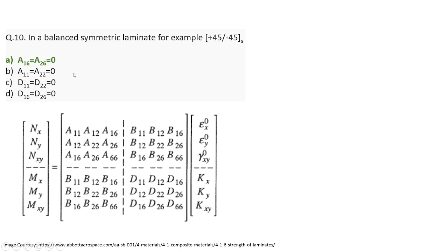But here, because these are at angles other than 0 and 90, in the D matrix, when there is a moment in one direction, there will be rotation in that plane because of this angle. Otherwise, for the force resultant, it is similar to before: when there is a force resultant in the x direction, there won't be any shear because of that. But for moment, there will be shear because the fibers are aligned not at 0 or 90 but at other angles.